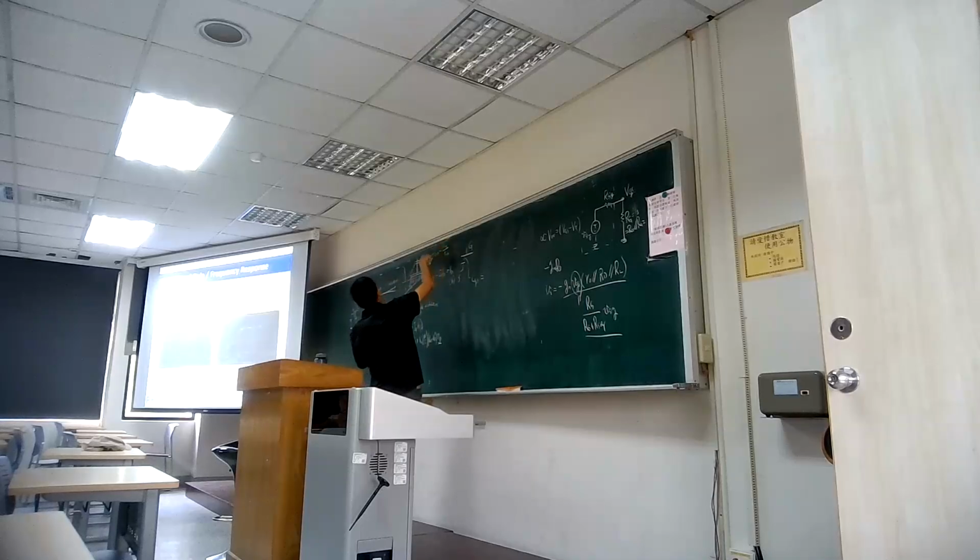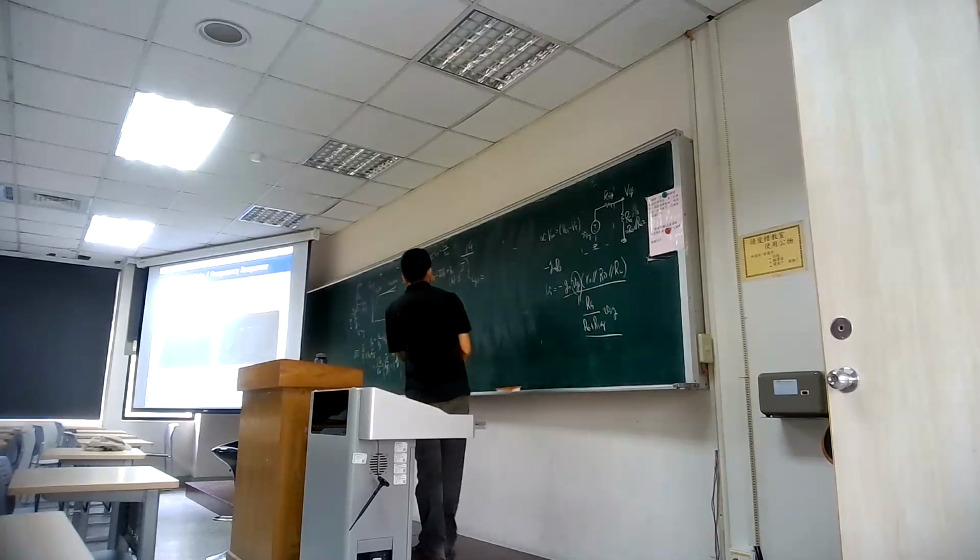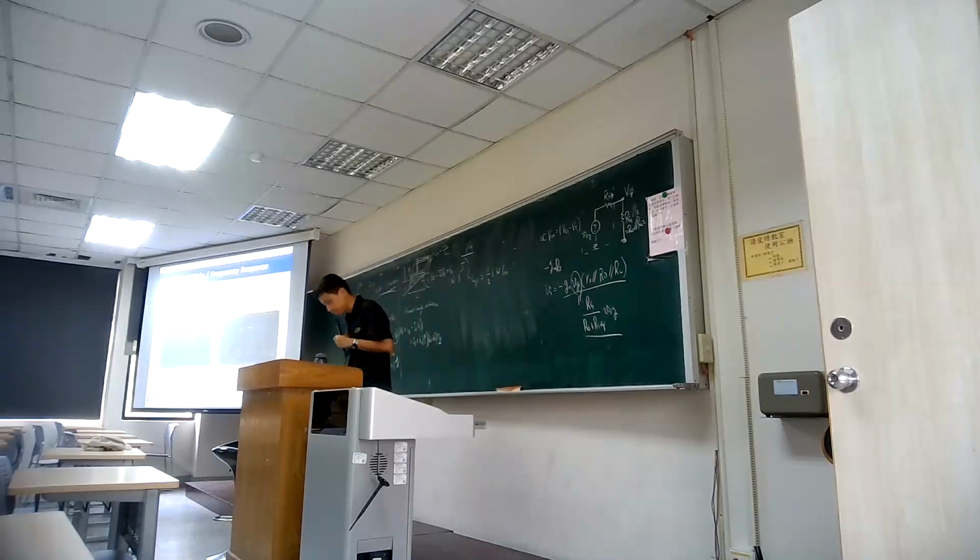And then what is the area? So we need to multiply with the area. It is the unit capacitance. So the area is here, we denote it by W, and then we know it is channel length L. So we just consider the half side, the gate to source side. So we can see that with this side, we get only half L multiplied with W multiplied with C oxide. So we get this capacitance like this.